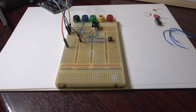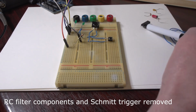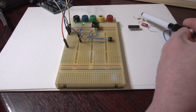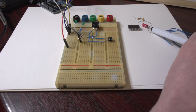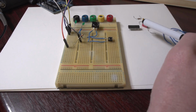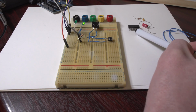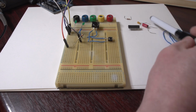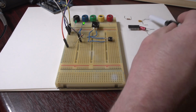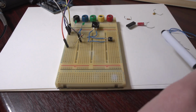Okay, so here we are back at the proto board again with the hardware, and this is to drive the software interrupt solution to debounce the switch. You'll notice straight away I've removed some components. I've removed the capacitor and the resistor of the RC, well at least the capacitor anyway, and we've removed the 220 ohm resistor to protect the switch, and we've also removed the 7414, or 7413 in my case, Schmitt trigger chip. So there's a bunch of components that we don't need anymore. That's a decoupling capacitor for the power supply, by the way, so you can exclude that. So we've removed 3 components here.